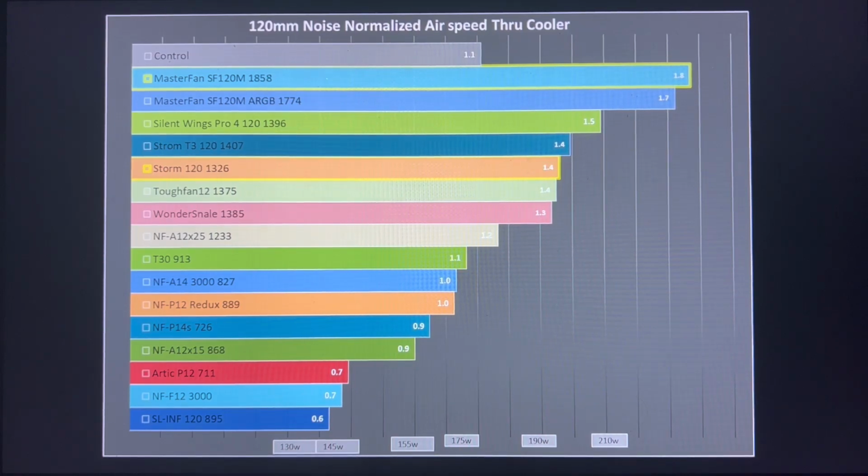So I adjusted my stock fans on it all the way down to the minimum RPMs at a 20% PWM signal and all the way up to 100% PWM signal, and found the associated wattage for pretty much every airflow. So that's what these are.